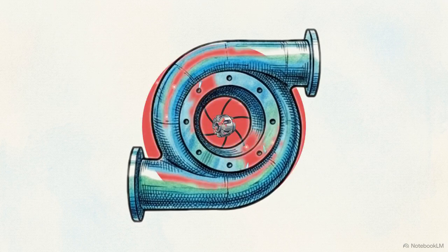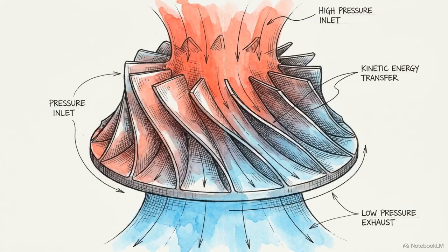Water enters tangentially at high pressure. As it moves along the spiral casing, stay vanes turn the flow inward toward the central runner. As the water glides over the rotating blades, it transfers momentum using both kinetic and pressure energy. The machine creates a massive pressure drop across the runner to extract the maximum possible energy from the fluid.